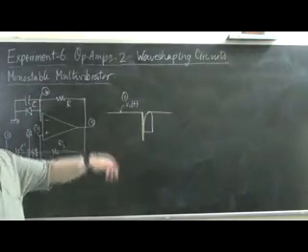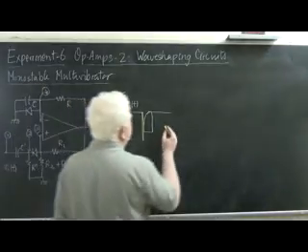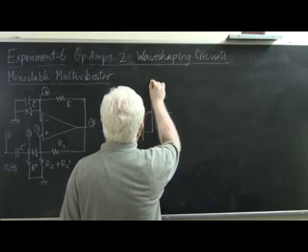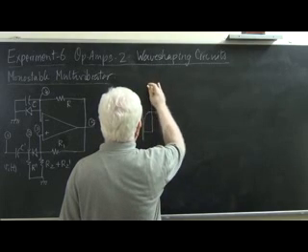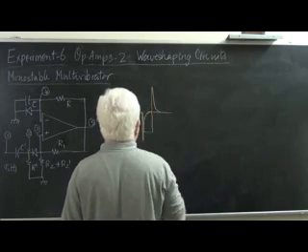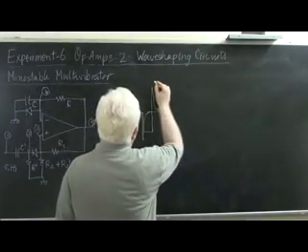And since the height of the positive going transition is the same as the earlier negative going transition, this will now give a positive spike of approximately the same magnitude. This then is waveform number 2.